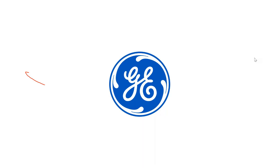They're both equally able to trip. And we actually use them together. So we've got an RTD function called RTD biasing, where we actually look at the RTDs and the current together to determine when we trip. And Terry's got some great case studies on that, where people set relays wrong and couldn't get it started.